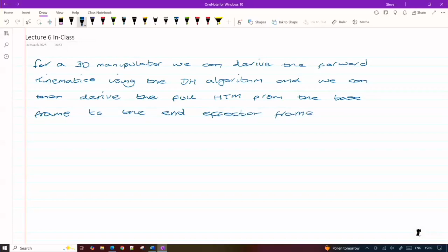So this gives us a transformation matrix that takes a point in our mobile frame that sits on our end effector. So this is our end effector mount point. This is the axis attached to it. We have a fixed base frame. We might have a series of joints in between these 2 points.